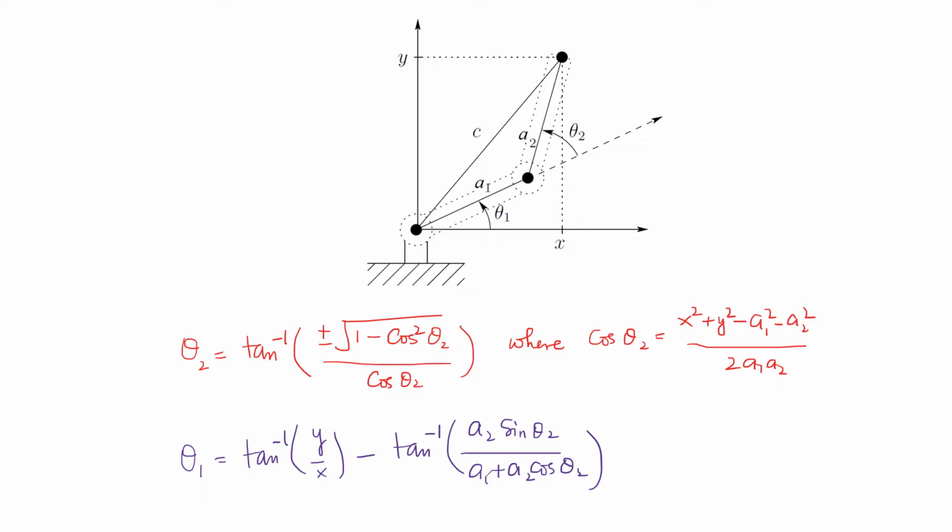Now in there, you must also realize that this is only a planar case, a very simple case, if I may say that. What if you have an n-link manipulator or multiple degrees of freedom exhibited by the robot? In that case, this scenario is going to become more complex, and probably we will require some more interesting ways to handle these situations, and we will discuss that. For example, the kinematic decoupling principle would be discussed later on. But this is one of the major issues which need to be resolved in robotic manipulators.